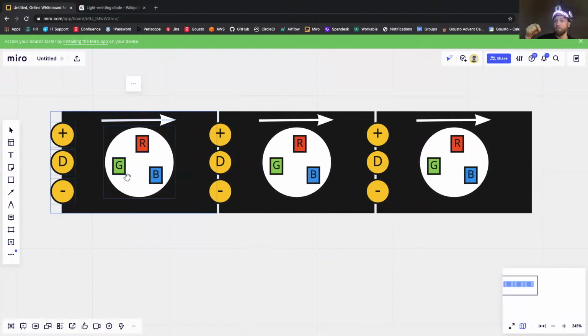So a pick and place machine, which is a robot, typically in Shenzhen, China, where a lot of these things are manufactured, will take these little surface mount components, those square packages, place them onto a printed circuit board, apply some solder paste, which will ultimately melt and fuse the connections between the input pins on this surface mount component to the printed circuit board so that the circuit can be completed and used.